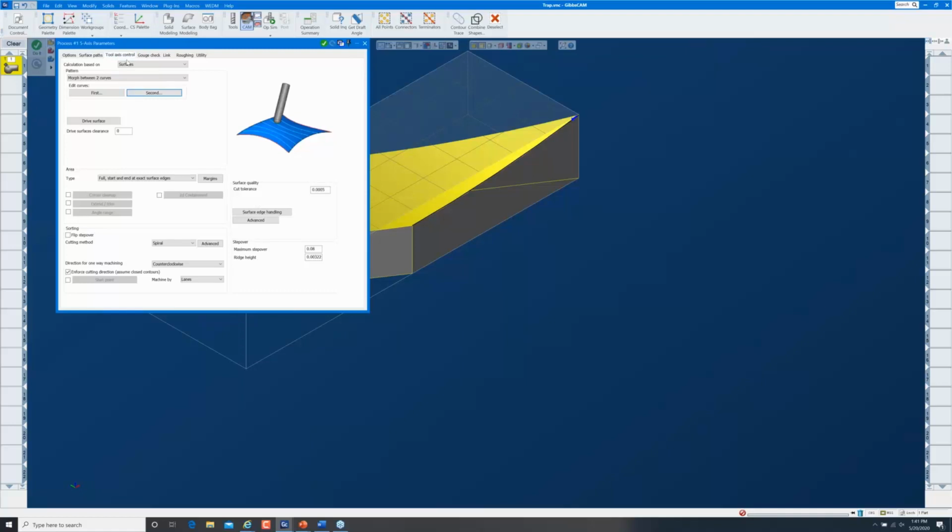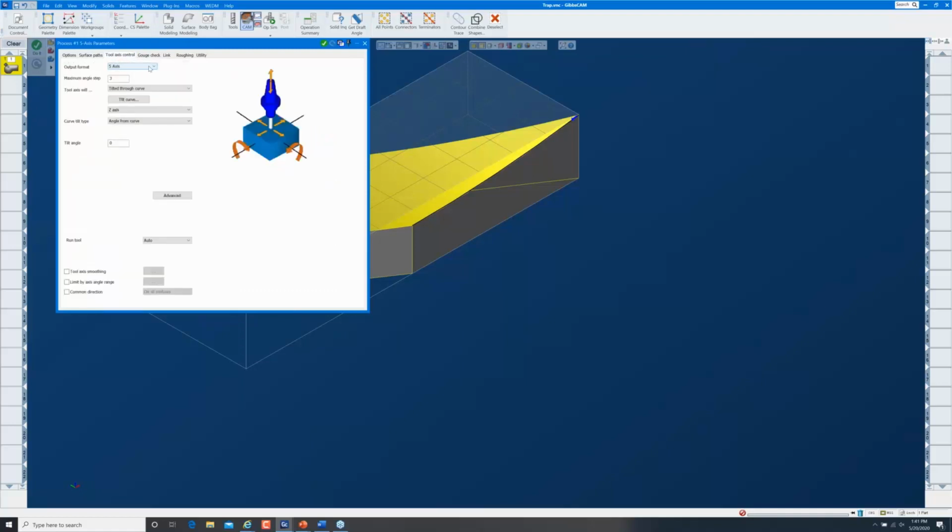And again, we can control this toolpath as 3-axis, 4-axis, or 5-axis toolpath very, very simply right here. I'll just leave it as it is, and I'm going to have the toolpath just stay normal to the surface. There's not a whole lot of 3D shape here. This is 3D shape, it's not flat. But let me create that toolpath.